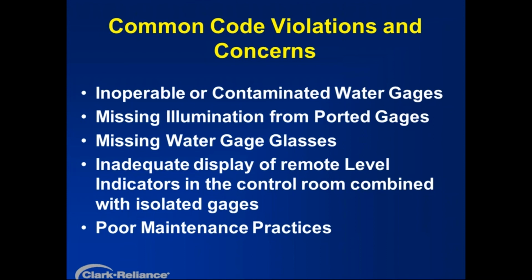Poor maintenance practices. Really, there's no excuse for this anymore. There's too much information out there on the web. If anyone has any doubt when servicing any of these instruments, we strongly urge you to seek out that original equipment manufacturer, find their instructions for torque values of fasteners, operating procedures, insulation, advice on the sensors themselves. Seek out the original manufacturer. They know best about what they recommend. Plus, replacement components improve over the years. It's always best to go back to the original manufacturer.